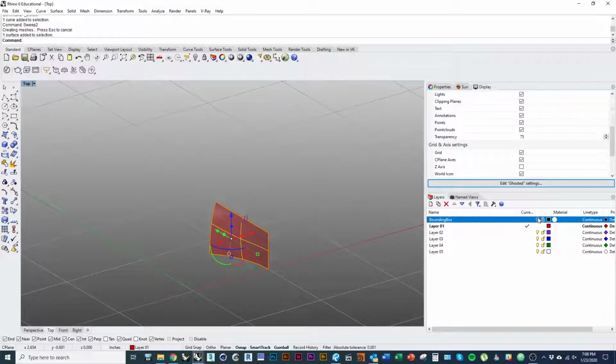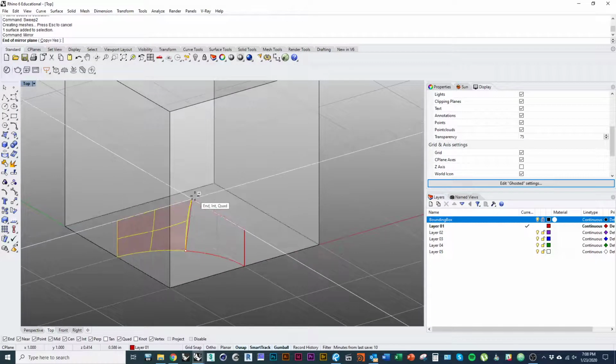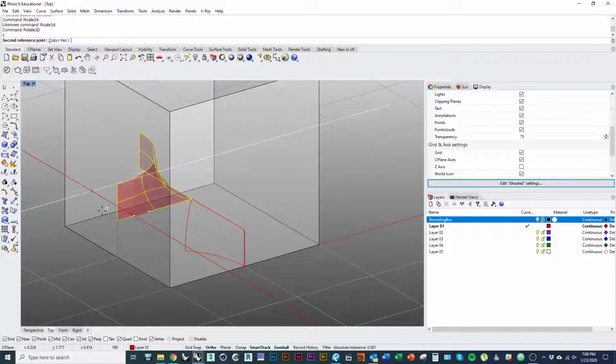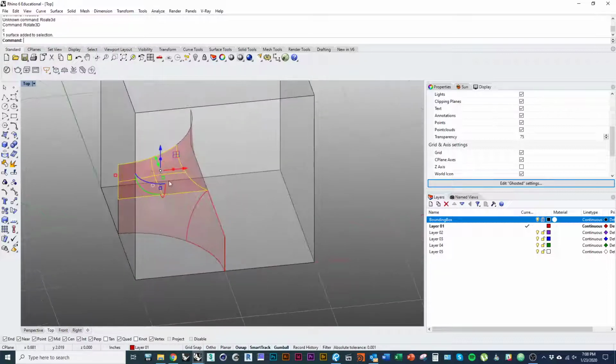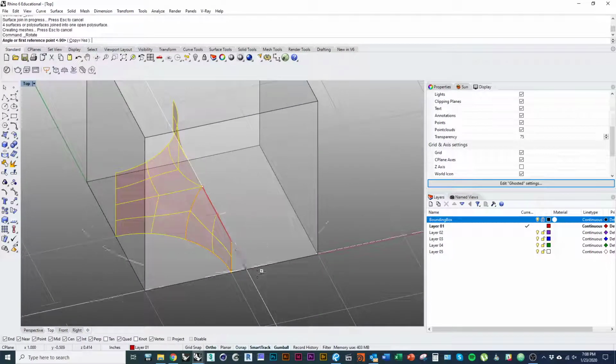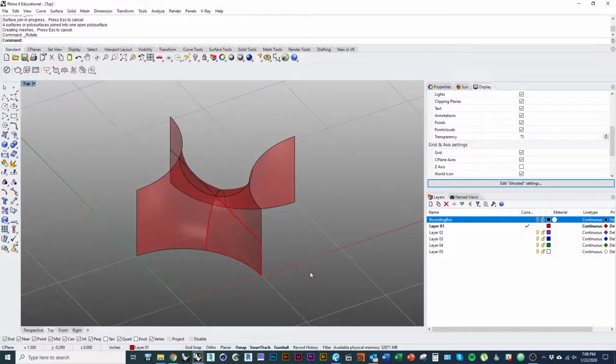So now we have that segment. If I were to go back and do like I was telling you, I would mirror that along that edge. Then I could rotate it, rotate 3D, along another edge, 180 degrees. And you can see before long we've already made the surface, right? So there's the saddle surface that I'm making.